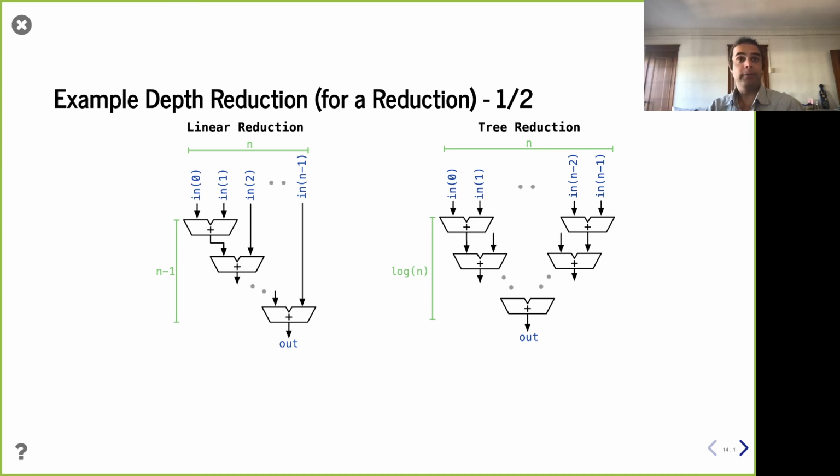In many cases, they can, right? For example, let's say you're doing something involving logic operators like and or, it definitely will do that. So why wouldn't it do that for add? Well, it goes back to the thing I said a few minutes ago about changing the design semantics, right? So for addition, if you add 2, let's say, n-bit numbers, in the worst case, the result could be n plus 1 bits, right? If I add 2 8-bit numbers, it actually could overflow and thus become a 9-bit number as a result of that addition.